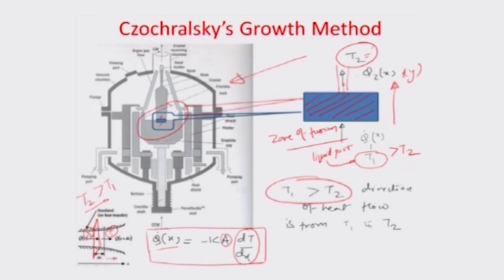It is called the latent heat of formation of the solid. So, the difference between the rate of heat flow into the zone of fusion and out of the zone of fusion is really the quantity of heat which is lost in formulating the solid from the liquid state.